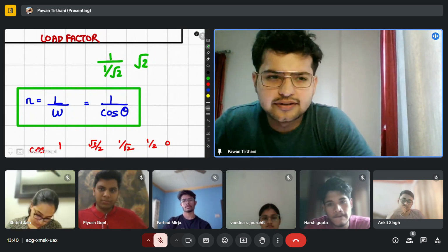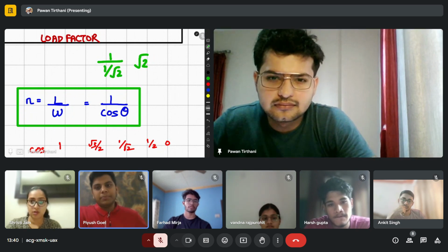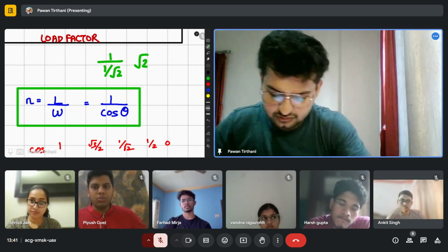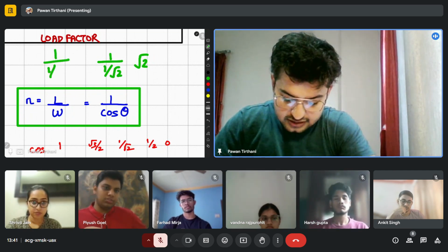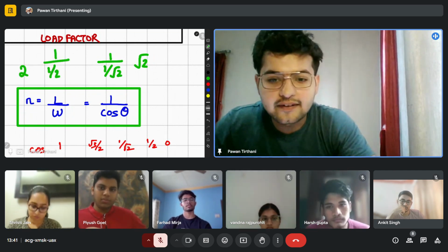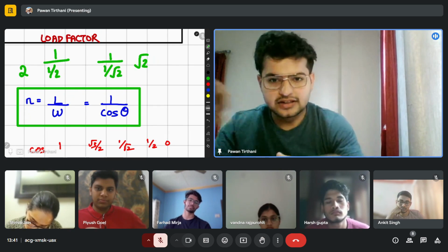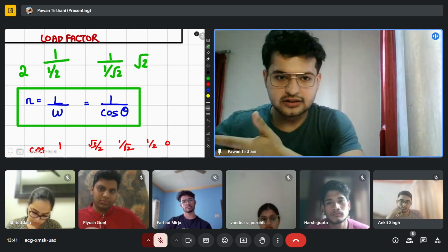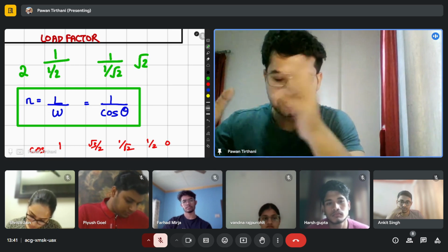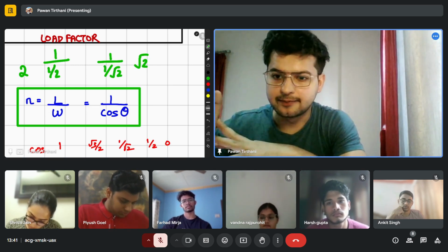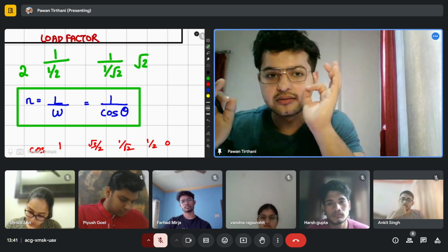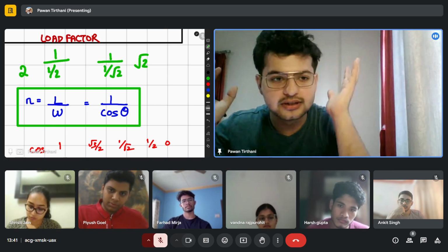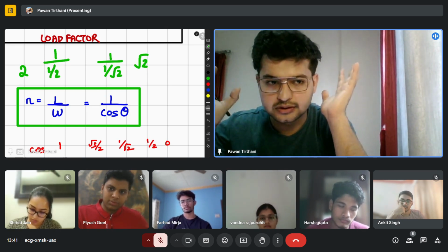60 का कॉस कितना होता है? 1 by 2. तो 1 by 1 by 2 is 2. 1 divided by cos 60. What is cos 60? 1 by 2. Load factor क्या आ गया? 2 आ गया. So we can very clearly see as my cosine angle of bank is increasing, my load factor is also increasing, right? So I should have the values of cosine in my head, और ये मुझे रटनी है by hook or crook. You will not have a calculator there with you. You have to mark up these values. Okay?